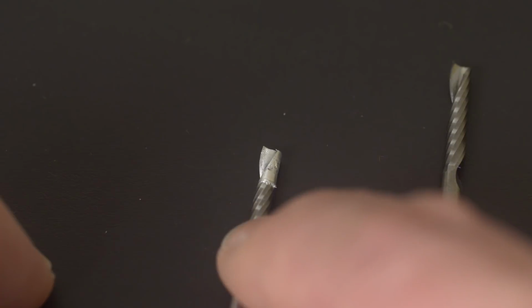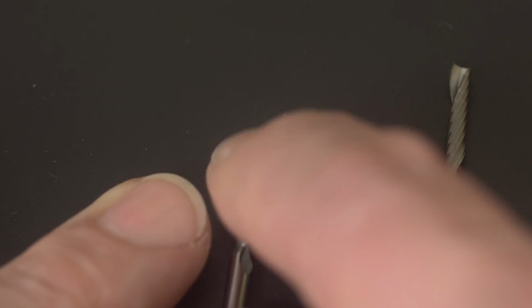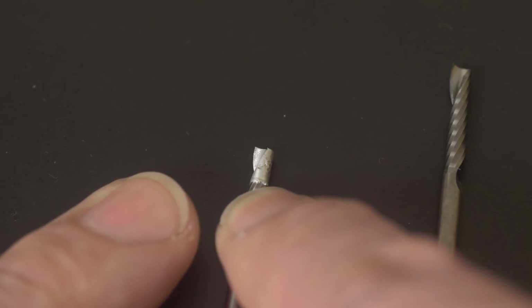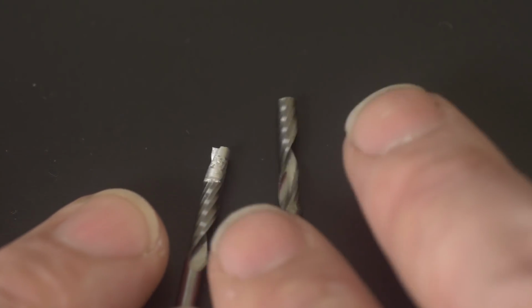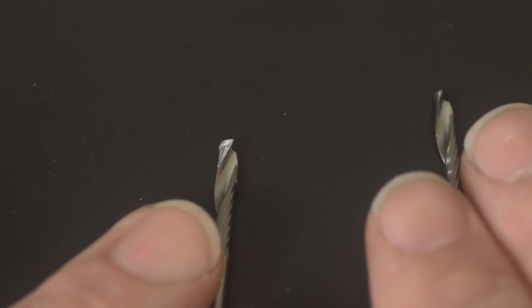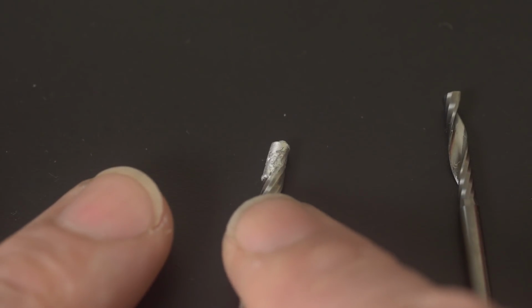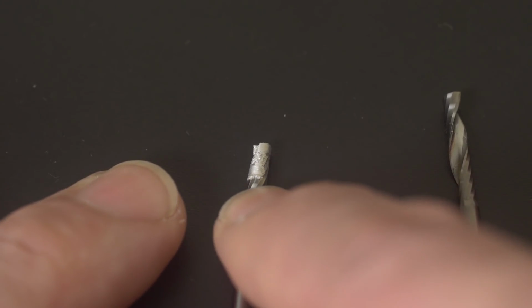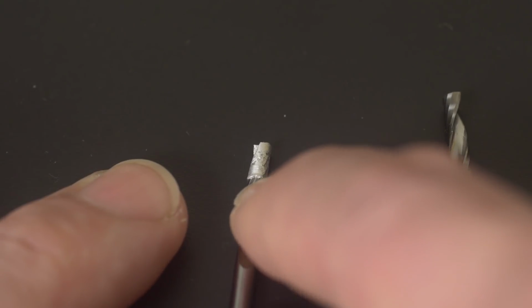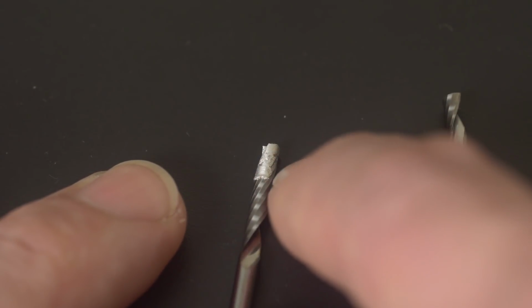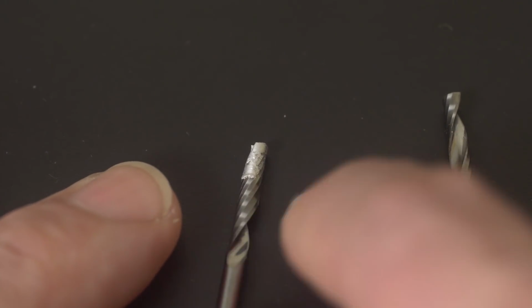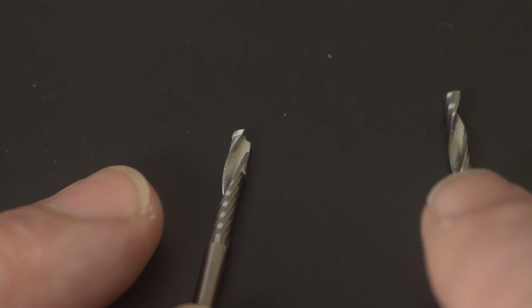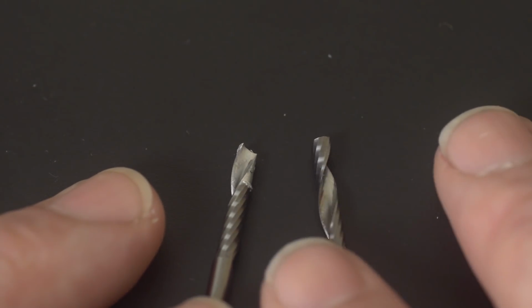Obviously, carbide is a whole lot harder than the aluminum, so I can chip off the majority of the aluminum that you're seeing here, and it will work okay for a little while, but it's never going to perform as good as a new bit would perform, and it won't be too long until this buildup happens again. And the reason for that is that the surface of the carbide has microscopic pores, which have now been filled up with chunks of aluminum. And so, basically there's an aluminum coating on this carbide at this point. So the reason you use single fluted bits is to try to avoid this kind of thing.